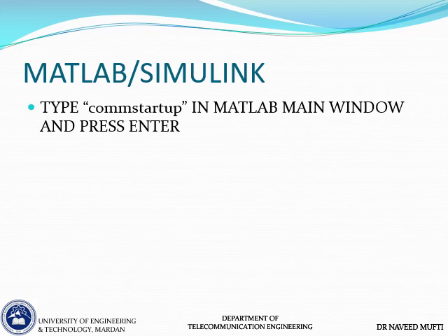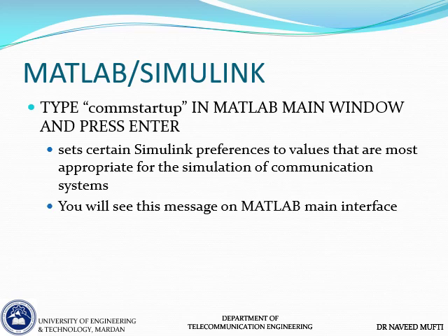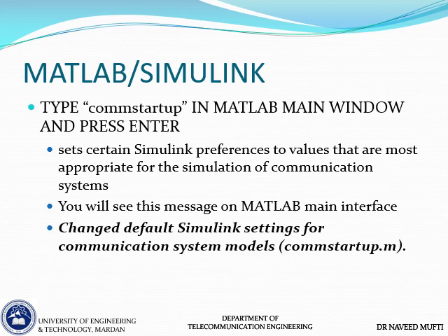So remember, make it a habit. Every time you start up MATLAB and you're about to do a simulation or create a communication system model, that is the first thing you need to do. What it does is that it sets certain Simulink preferences to values that are most appropriate for the simulation of communication systems. You will also see this message on the MATLAB main interface: change default Simulink settings for communication system models. When this message appears, it's a confirmation that the command has been accepted by MATLAB.